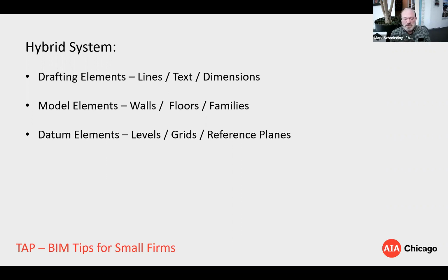And then when you look at model elements, if I'm putting in walls or windows, I'm actually using the model elements, and those will show up in every view: perspective, plan, section, elevation. And then in those views, I can highlight it by drafting on top of it. And then the last kind of view is a drafting view. You can pull open in Revit what would be like a piece of paper, tearing off a piece of paper and just drafting. Typically it's used for details. I use it for charts and all sorts of stuff. So you have both those elements.